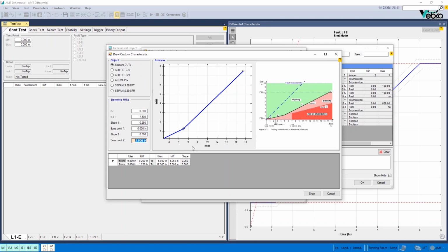To better understand the parameters of the Data section, on the right side of this window, the characteristic curve shape of each relay is sourced from its corresponding catalog and the parameters are determined schematically. After entering this information, the differential characteristic curve of the intended relay is displayed in the Preview section and in the box at the bottom. The start and end point information are mentioned according to I bias and I differential. Also, the slope of the line is displayed in a slope section.